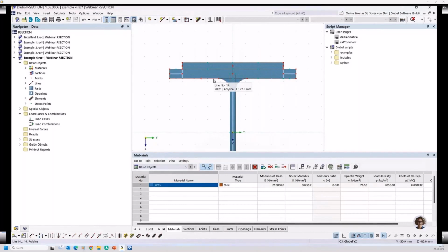It's because the element edges correspond to the boundary lines of the respective parts, but the parts are directly adjacent to each other, so that no subpanels are created for the upper flange and for the flat bar. If I want to create subpanels for the flange and the flat bar, a distance between the parts with their elements has to be created.